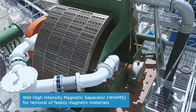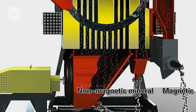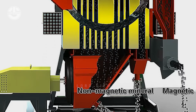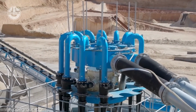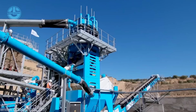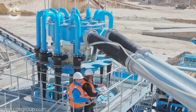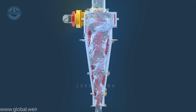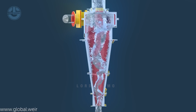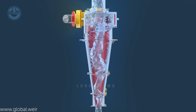Next, the wet, high-intensity magnetic separators further purify silica from ferromagnetic elements by attracting them with their magnetic field. Then, the feed enters the hydrocyclone, and centrifugal forces push heavier solids outward, leaving behind concentrated particles. The vortex finder creates a swirling motion, and the fluid exits through the overflow, while solids exit at the bottom.